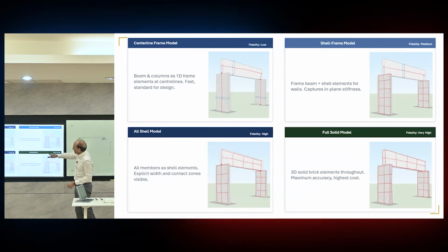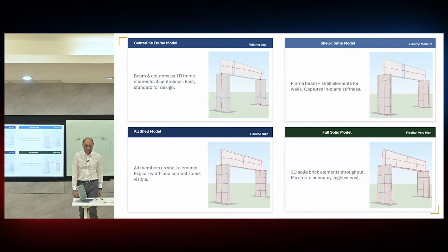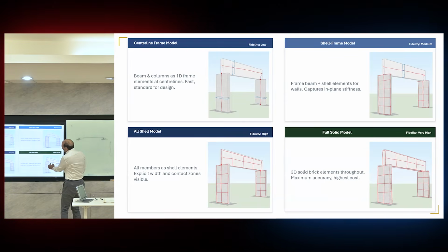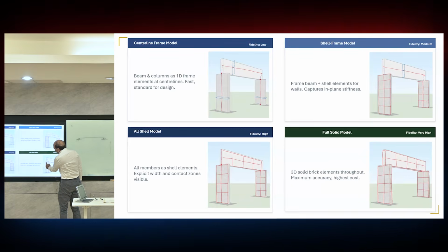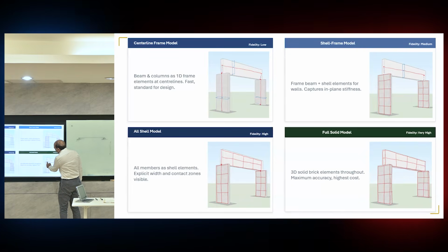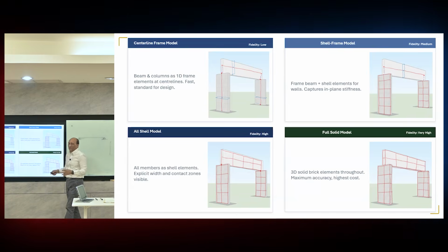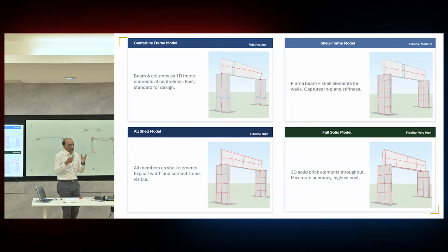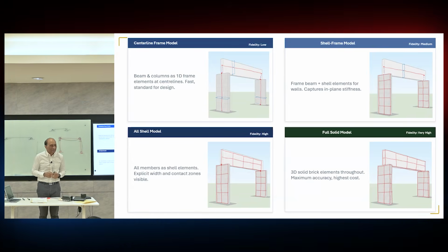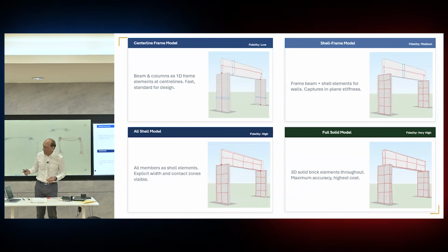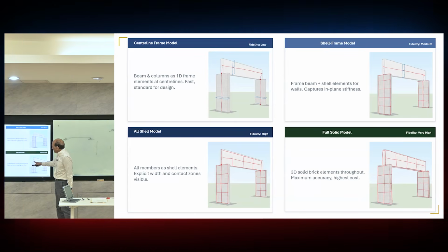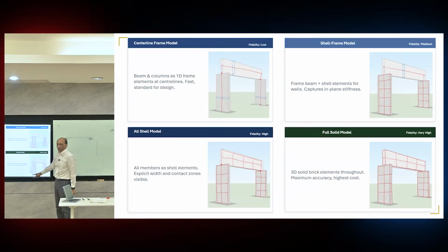So now we know that, okay, at least these 4 models are possible. Now, these 4 models are possible, but here you will find the problem between the meshing not matching, and solid. So we need to do a lot of careful meshing to make sure that things are connected and aligned to each other. Otherwise, actually, this model is not correct because solid nodes are here, this node is center, they will not connect.